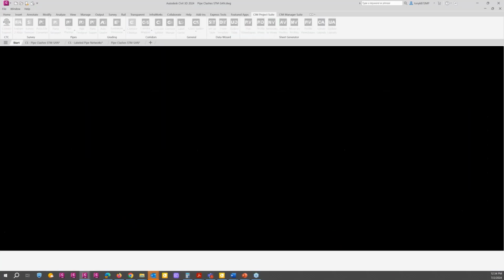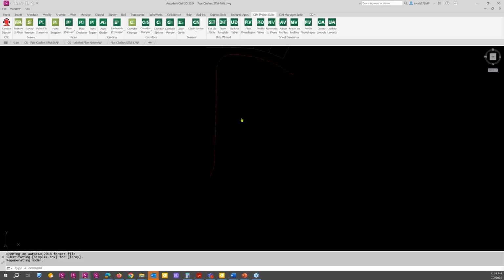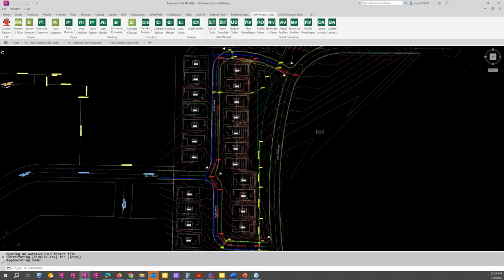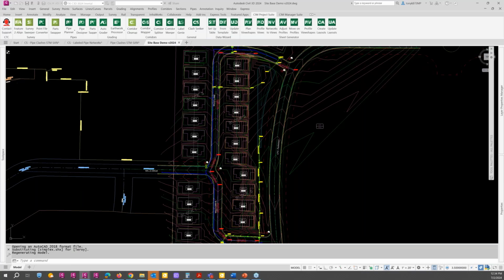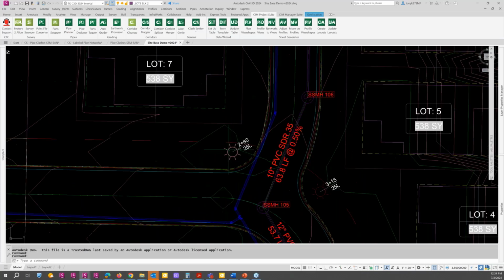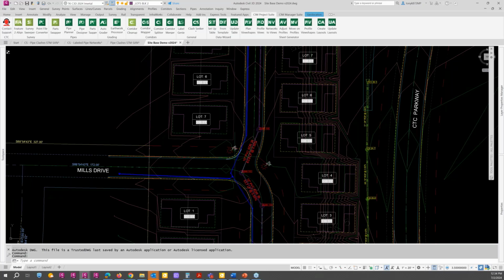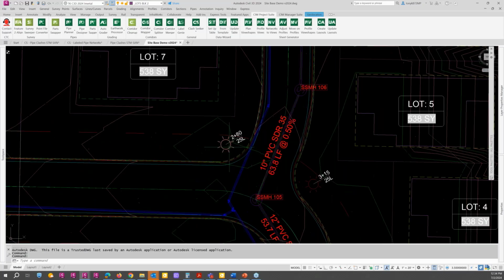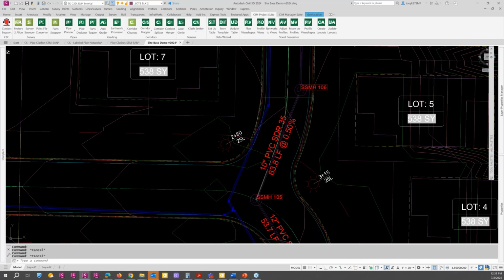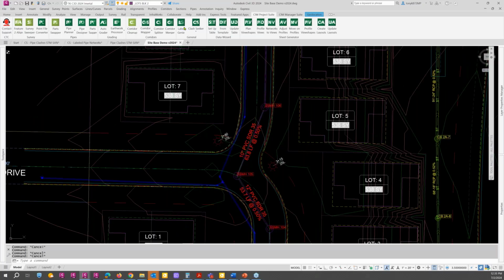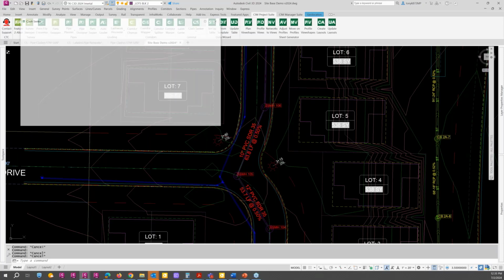Jumped on me. So if we open up this drawing, I think there's some light poles. There are. Okay. So we already know we labeled them. We know where they're at, but if we just want to make sure they're within the right of way of the alignment, we could do that with these blocks. So that's a block, as we see. And then this alignment, I will do that just to show us. So let's say this is, I don't even know, 30 foot, 33 foot right of way. So that's when I would set my buffer.